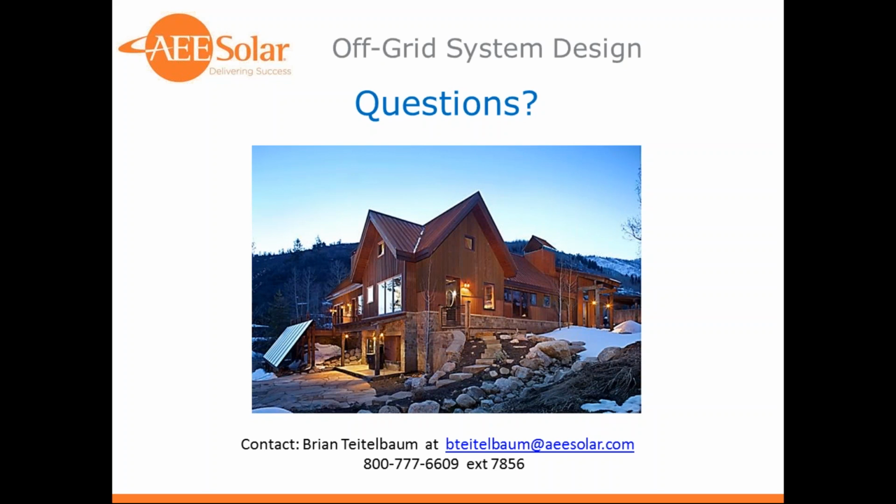But essentially, in the grid tie setup, if you have a 4 kilowatt grid tie inverter and you put 5 or 6 kilowatts of PV, the inverter just limits it to 4 kilowatts and doesn't use the additional power. In an off-grid situation, the inverter will try to power those loads up to the point where it just overheats itself and shuts off. So be aware of that. You don't want your customers calling you on Sunday morning because their power's out.